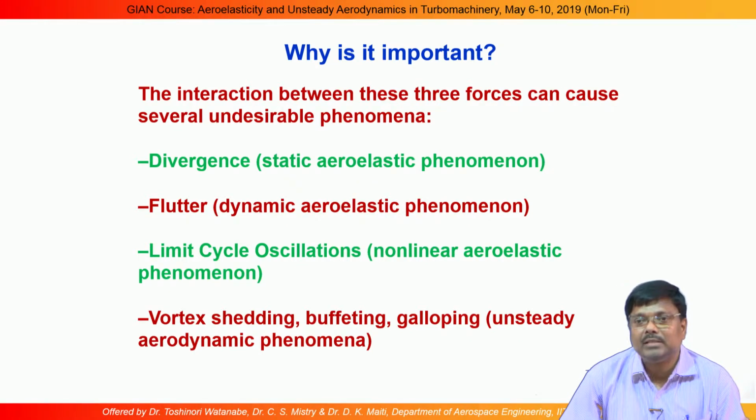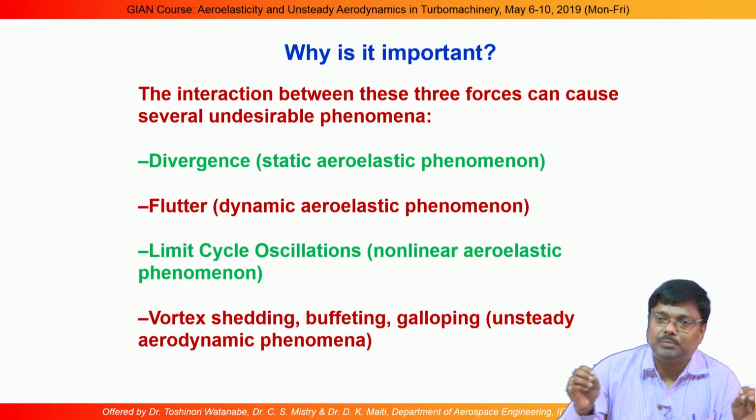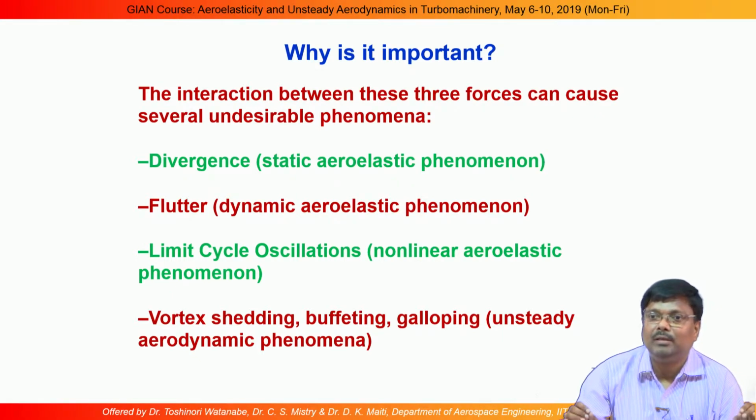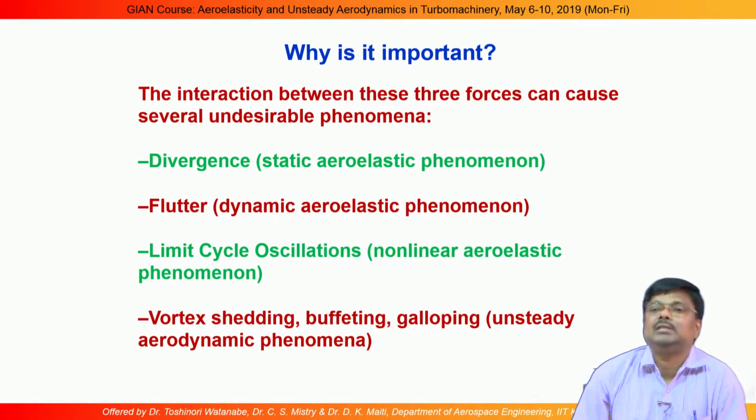The configuration is slightly different, the CG position is different, it is longer, and the inertial characteristics are different. When that missile was put on the earlier design, it was found that flutter was happening within the design envelope.